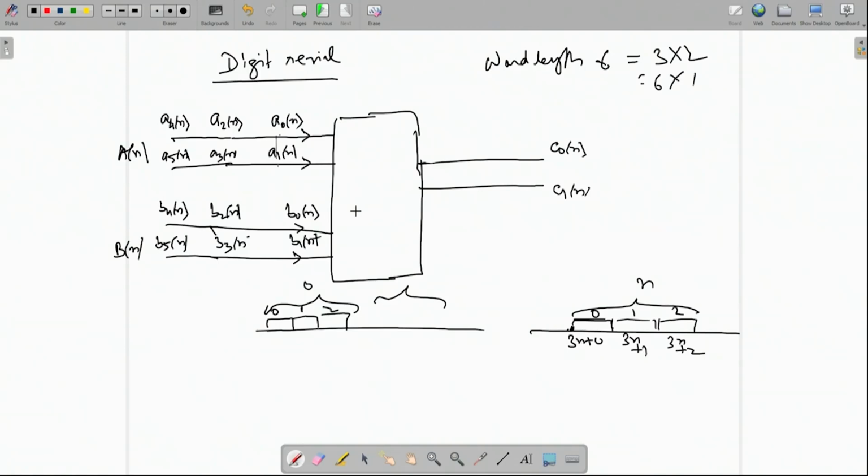Similarly, in terms of speed, in the fully serial case I was using a clock 6 times faster: 0, 1, 2, 3 up to 5. Now I am using only 3 times, so the input clock is not going up that much, and I am not losing that much on speed. But I am also not gaining too much in power, because I am not able to bring down the power by a full 6 times, as in the serial case where 6 parallel processors came down to 1 processor.